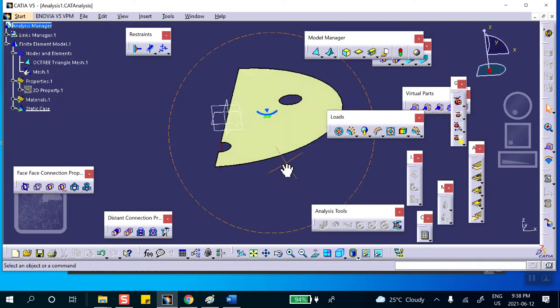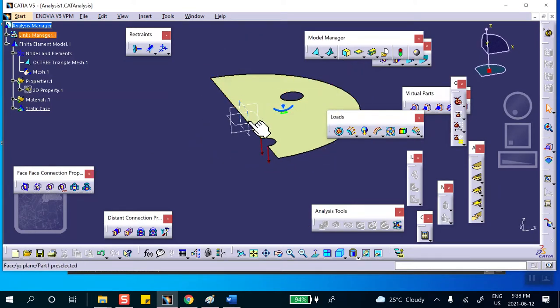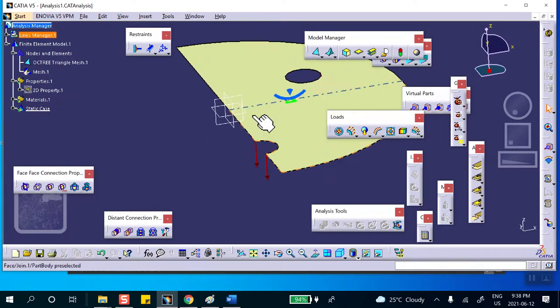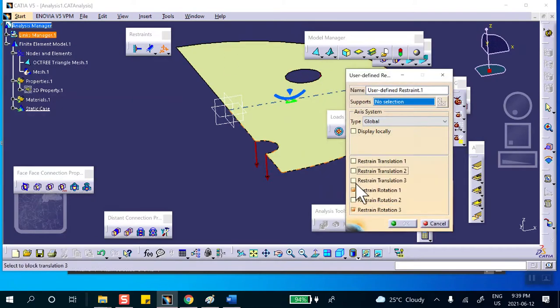And these things are in planar symmetry. See that? These three edges, this edge and that edge and that edge, lie in the YZ planar symmetry. So we know how to handle that. They do not move in X, and rotations are exactly the opposite.